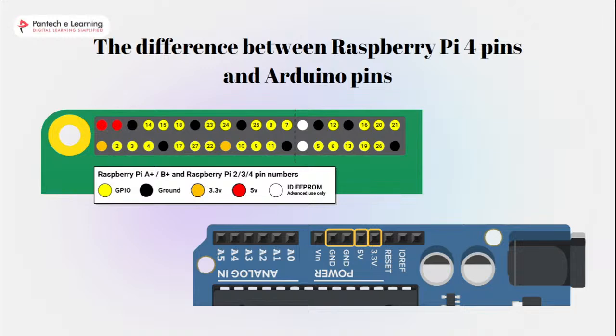For example, Raspbian. So while Arduino has a microcontroller, right? That's something you can't see on the board directly. Many hardware functionalities from Arduino are not present in a Raspberry Pi board. You don't have analog pins on the Raspberry Pi board. If you want to use an analog sensor, you will have to use an external ADC and get the value using the I2C or SPI protocol.